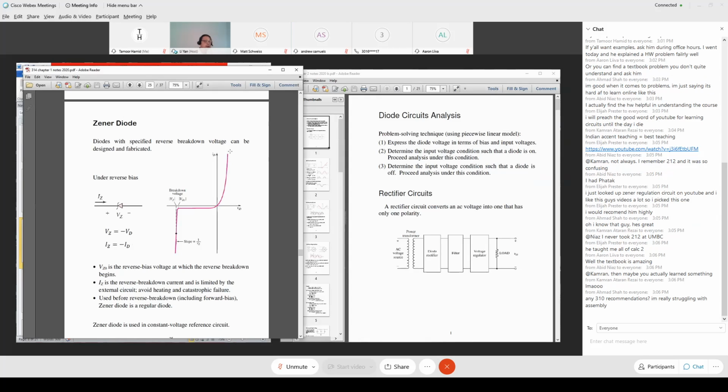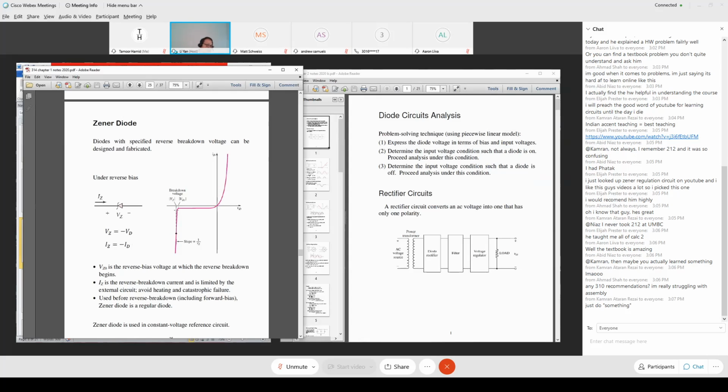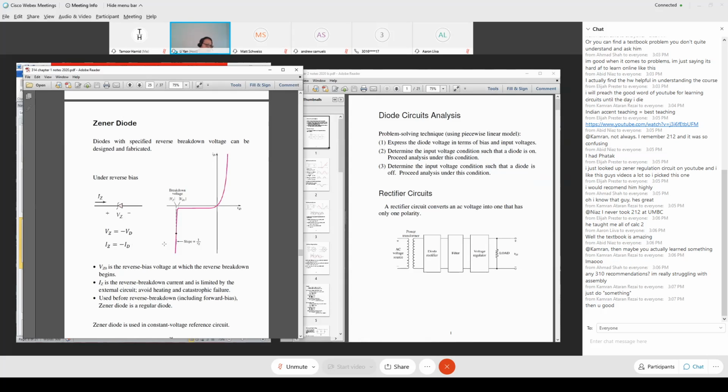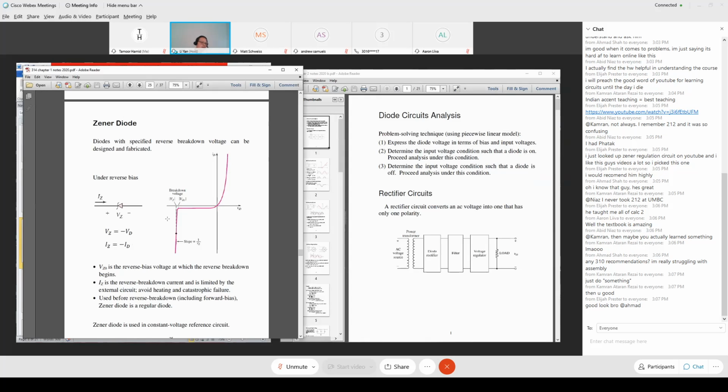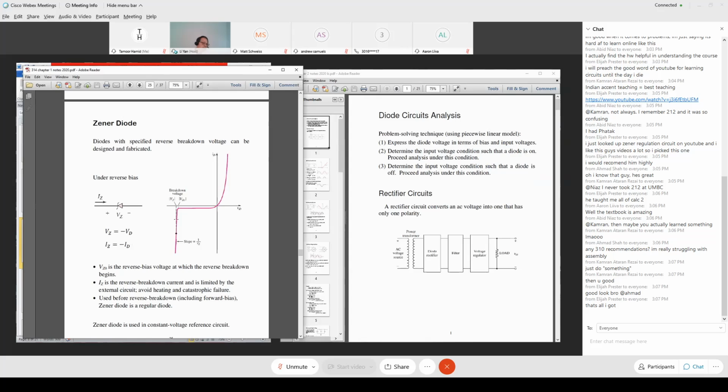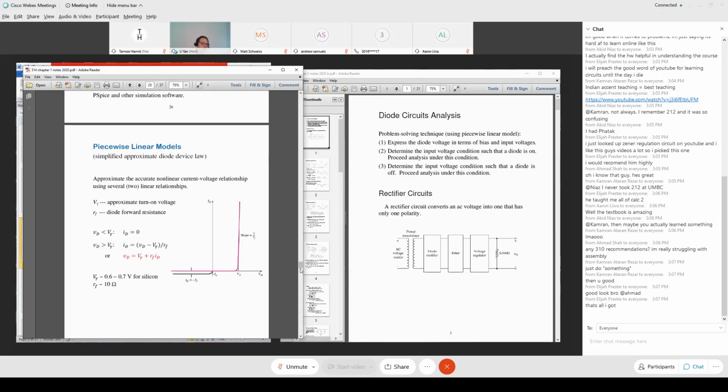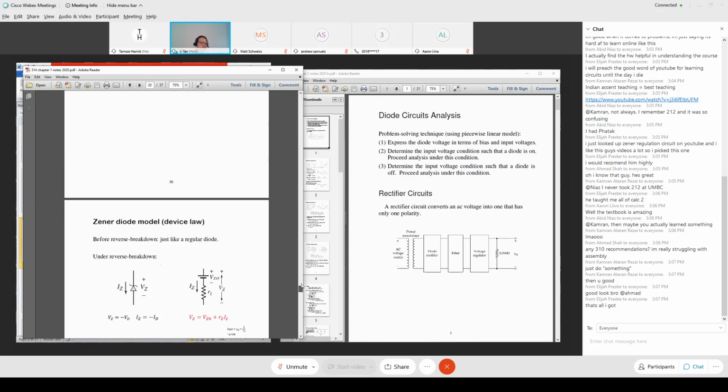Ideal, for the point is when you apply this ideal, refer to what? Why do I say it's not an ideal Zener diode? It's not ideal Zener diode means what? If the ideal Zener diode, this straight line is vertical. If non-ideal, this straight line has a finite slope. It's only referred to that sense. It's within the reverse breakdown region. How do you describe ideal, not ideal? It has its own definition.